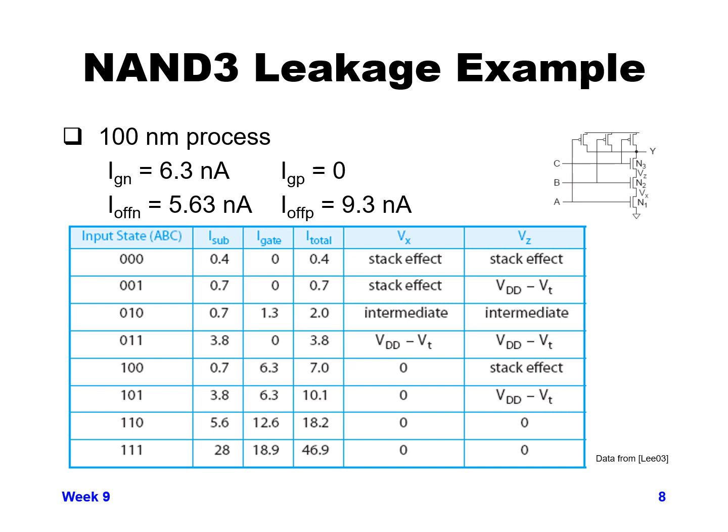So just keep in mind, there can be almost a factor of 100 difference in your leakage depending on what your inputs are in this particular case. The stack effect really can help you, but if your logical input values are not turning off the stack, then it doesn't help you at all, and you get the maximum leakage.